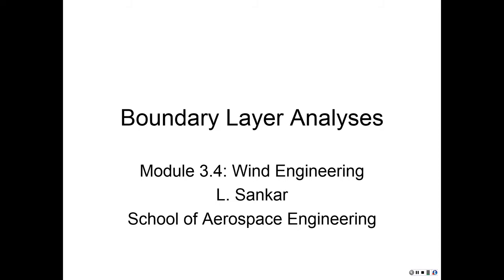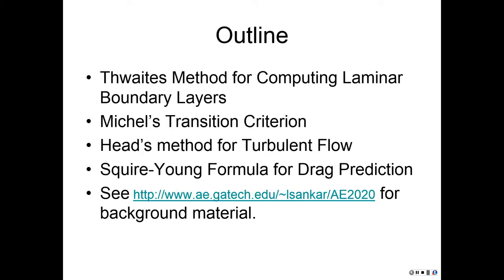So now we turn our attention to boundary layers, because without knowing what's going on in the boundary layer, we cannot compute the drag. So panel method gives the lift. To compute the drag, you need some kind of a boundary layer analysis. It could be done in a number of ways. In many of the commercial programs and also public domain programs, such as X-Foil, this is done using some simplified empirical approaches. So we briefly review these empirical approaches in this module.